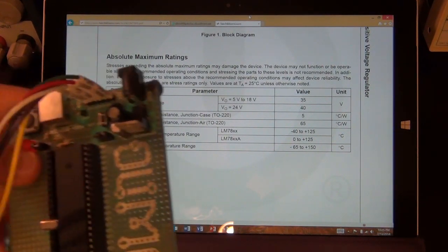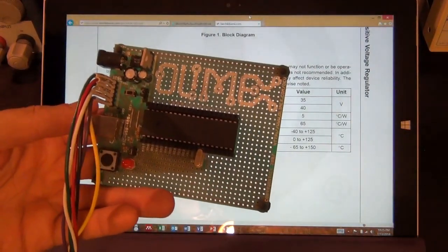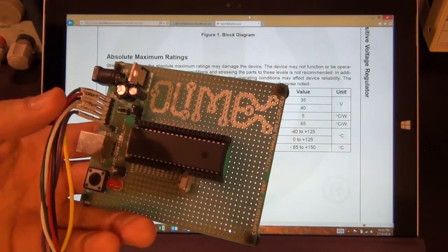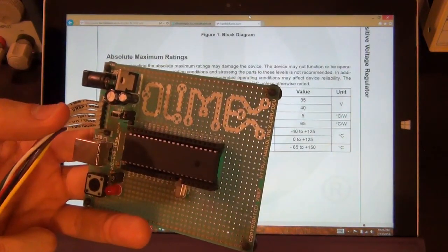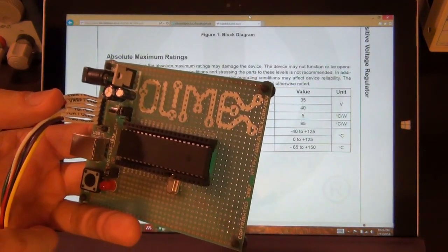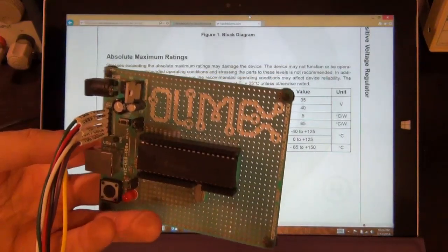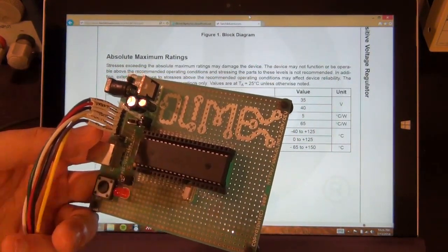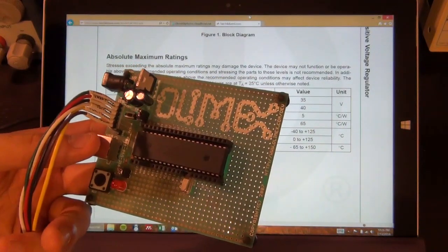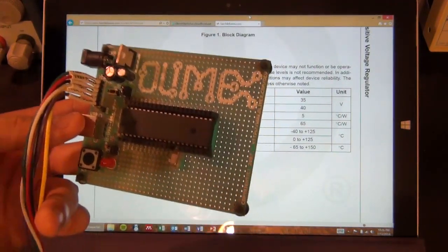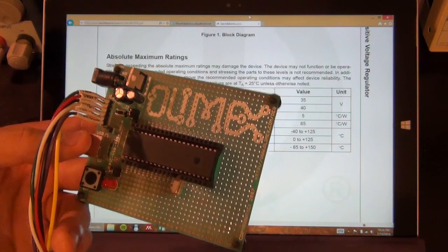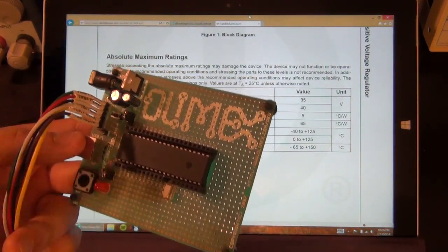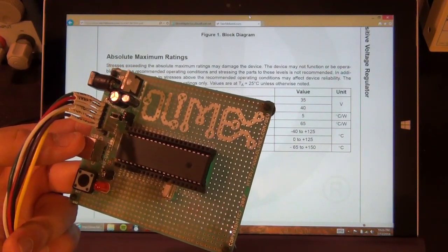So this immediately tells us that we shouldn't make that mistake, and we shouldn't try and power it through the regulator. We'll have to have a whole separate power supply for it, perhaps a switching power supply. So I'm going to use my Rigol power supply to power the LEDs, and I'm going to just use the USB to power the microcontroller itself. But be very careful not to connect those two powers together. You can't connect the 5 volt power of the computer to the power supply because they're not exactly the same, and there's going to be some current sinking and sourcing, so don't do that.